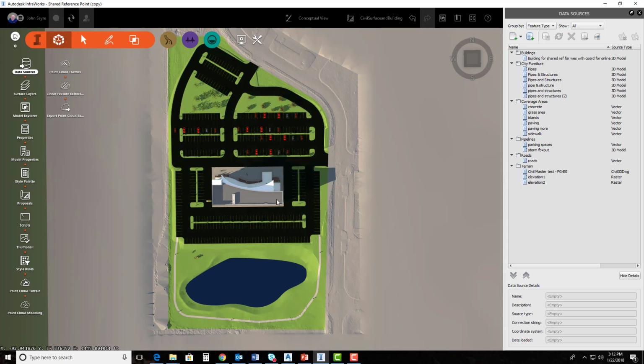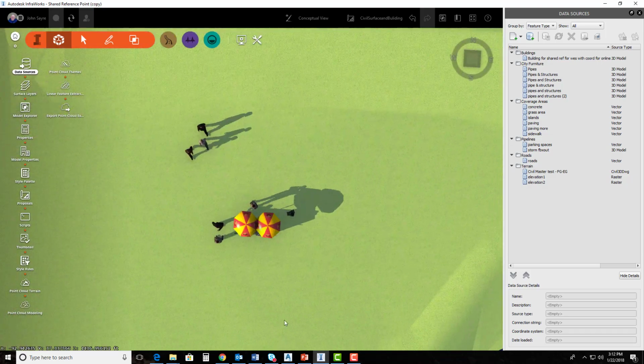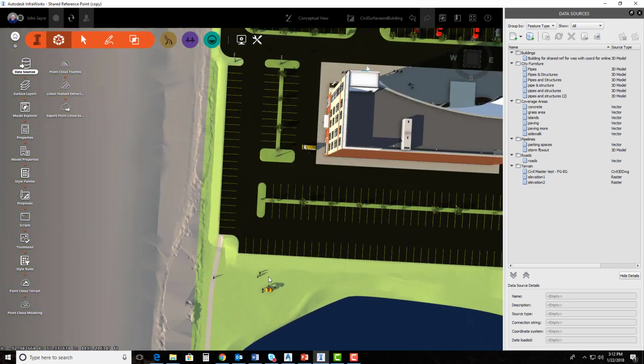So we'll be using those quite a bit later on. Whenever we go to make this surface here for the asphalt, we go to make it transparent. Those surfaces will have come through from InfraWorks. I want to drive the point home that we use InfraWorks as the aggregator of data here. So I've got my Revit model, I've got my parking stripes. I've even got my hot dog stand here that I brought in, just some people milling around.